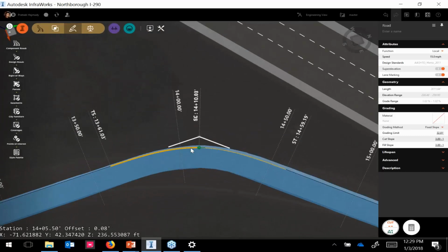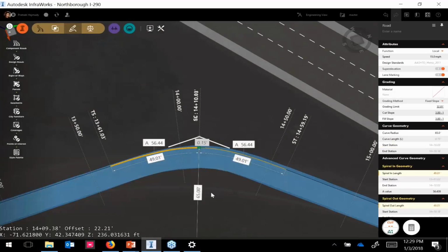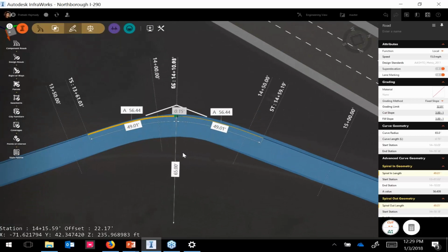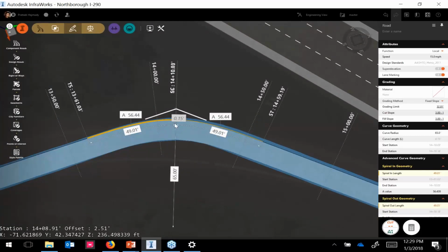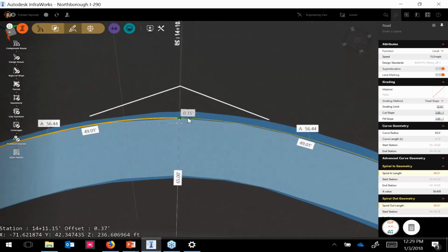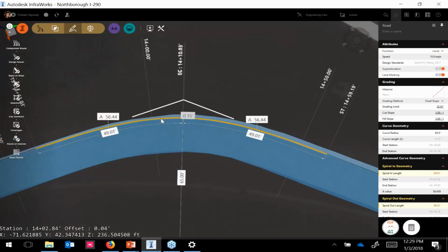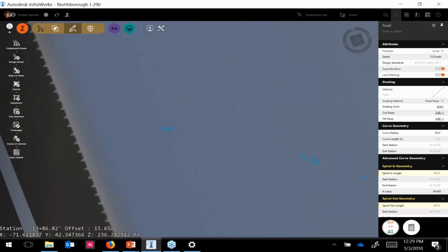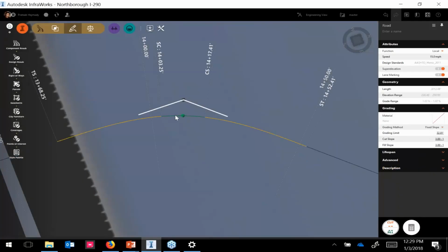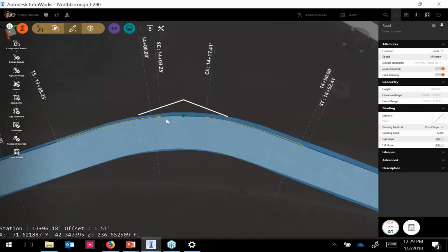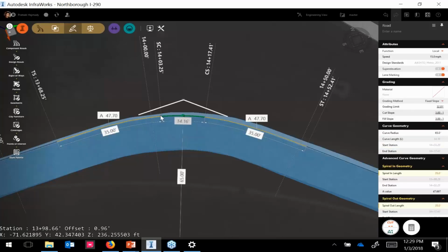All right, so let's come back to this spiral that was created earlier. So again, you see here that when you select a spiral curve spiral combination, you do have a curve here, based on the limits you had with the geometry. It was a fairly short curve, but I could go ahead and change the length of the spiral to say 35. As that got regenerated, you do see now that the length of the curve is slightly larger.